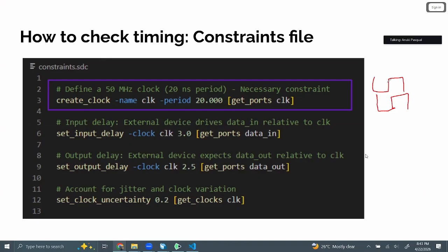It's very small compared to the clock period, but it can still have an effect. It might also be unbalanced like this sometimes, because it might not be perfect at all times. So if we want to account for that imperfection when doing the timing analysis, we can set a clock uncertainty value here. But for FPGA work, it doesn't matter too much.